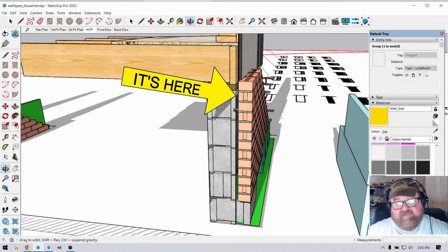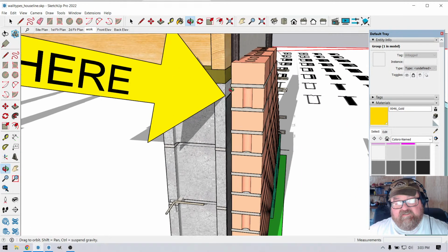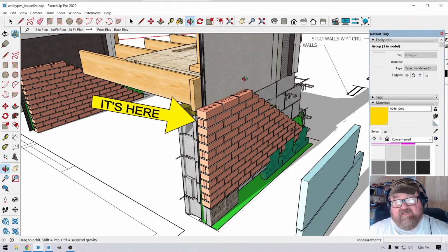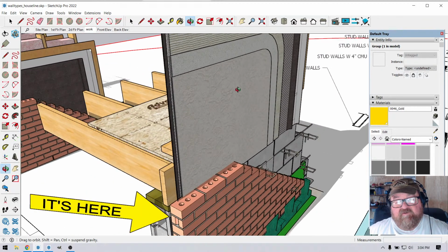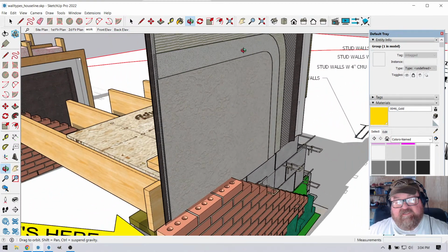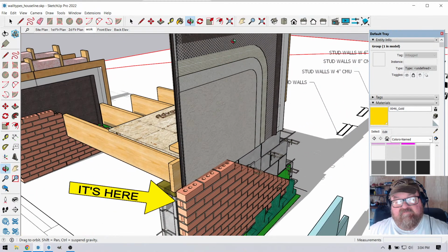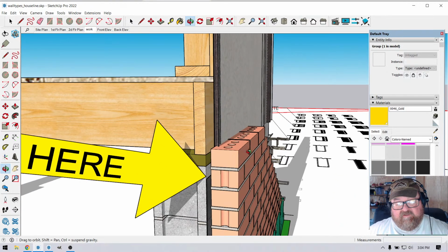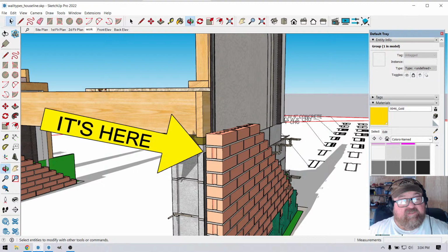But anyway, again, you see the house line. Even if you have brick on the foundation, this is still the house line, the corner of the house, because the brick is a veneer and the siding is a veneer. I think they're trying to show EIFS like a stucco. EIFS is like a synthetic stucco, yeah, because they've got all these different layers. And there would be this brick. This layer wouldn't be here.